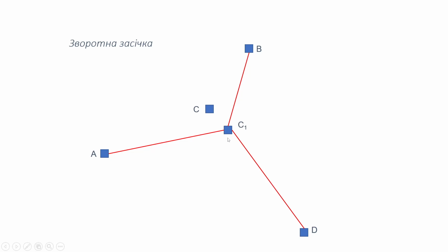When we use not a theodolite but a total station, this free station method is very popular because we can put our total station on the site, just orient our total station to line A and to line B, for example, and to line D, and then the total station calculates its coordinates itself.